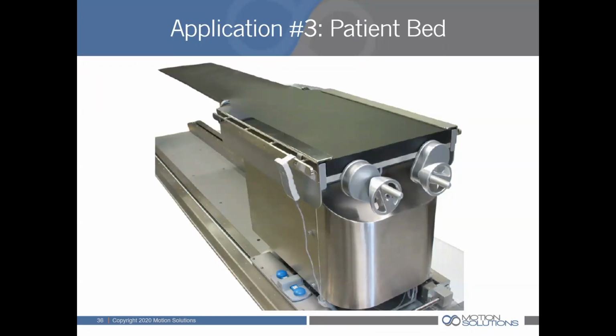You can imagine the patient laying on the carbon fiber bed, the part that's overhung off to the front of the bed. The reason they do that is because for several different types of medical applications, you don't want any metal in the treatment area. The carbon fiber doesn't show up. It's very radiolucent if you're sending radiation through the patient, or if you have any type of magnetic field, the carbon fiber doesn't affect that. So you lay the patient on the carbon fiber bed and you extend them into the machine to do whatever treatment you're doing.